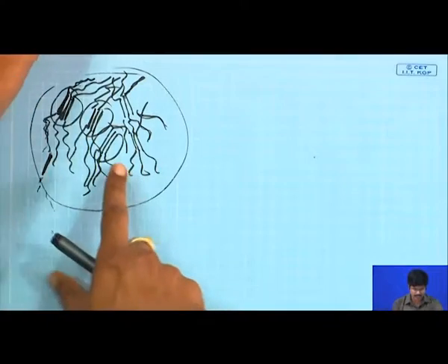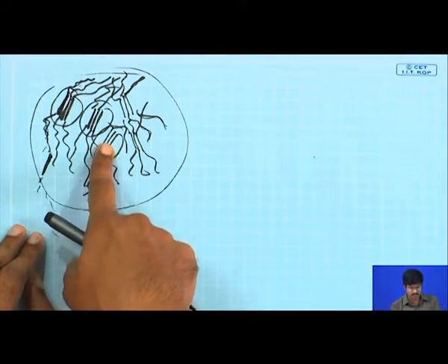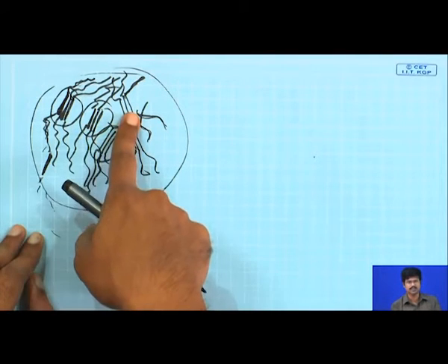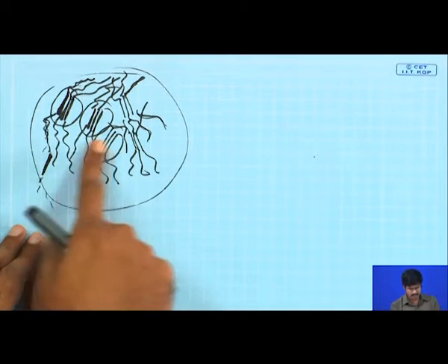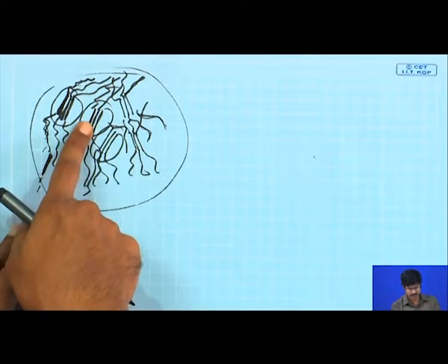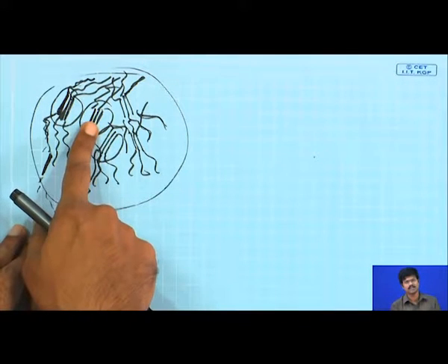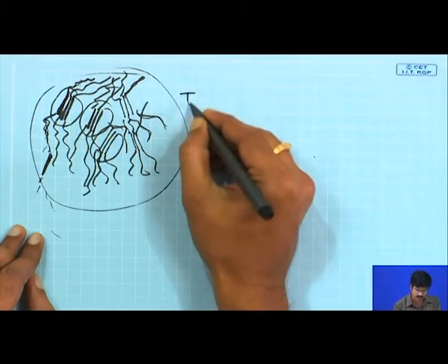So, obviously, you have these cross-links, and they will give you the stiffness of the material, and also the tensile strength of the material. But when you heat this material up, the interaction between the different chains, the hard blocks in the domain, will disappear, because the interaction is a hydrogen bonding interaction, which is reversible. So, if you heat it up, the material becomes processable. That is why it is a thermoplastic material,